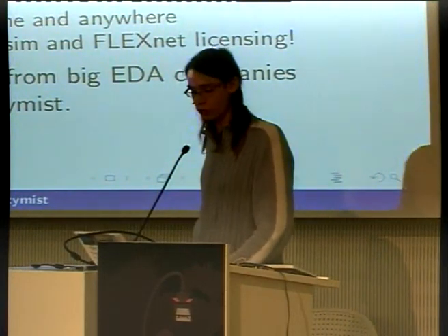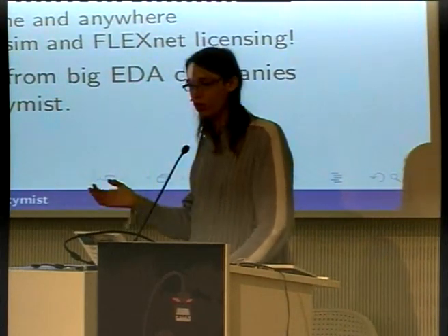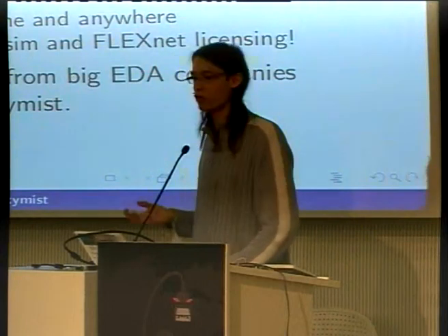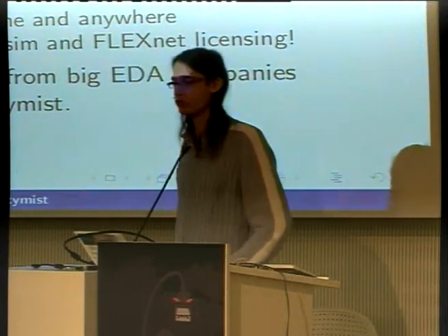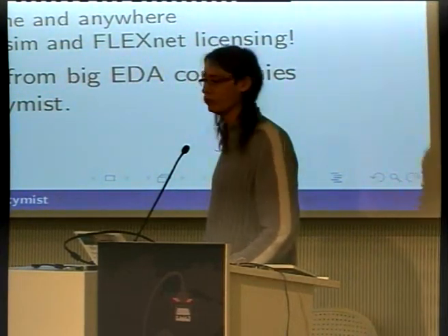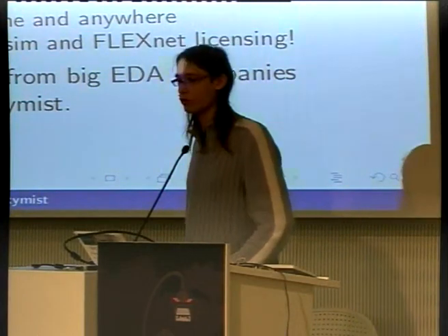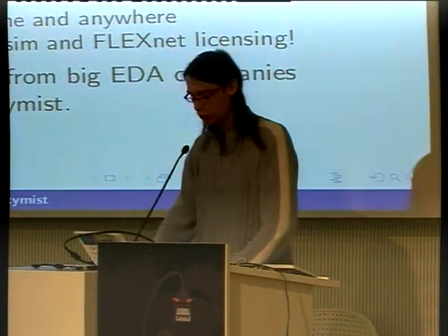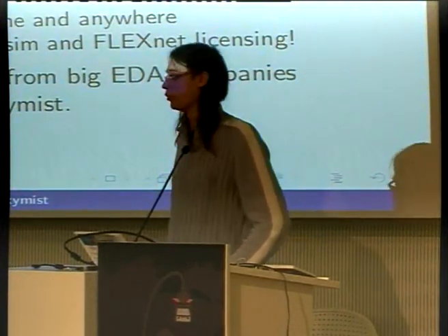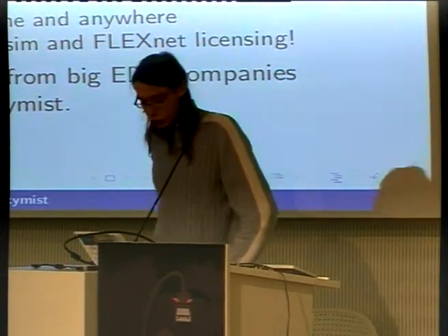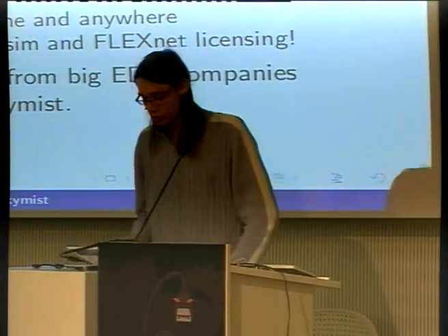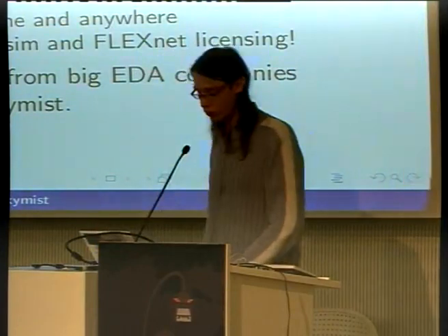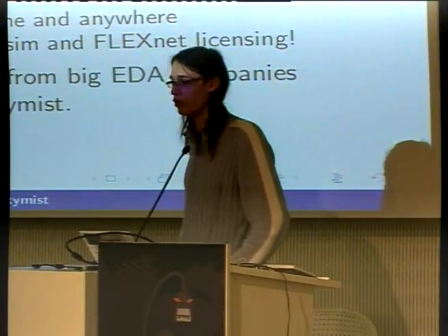Verilator is very innovative because it's actually compiling Verilog code for your CPU. So it gets you a very fast simulator. The problem is that it has a lot of bugs. So I didn't use this one much because it took me too much time to figure out if the bug was in my design or in the simulator. But Icarus Verilog and GPL Cver are pretty reliable. They're very light. They can run without a hitch on small laptops like this one. So you can really debug your Verilog code wherever you are.